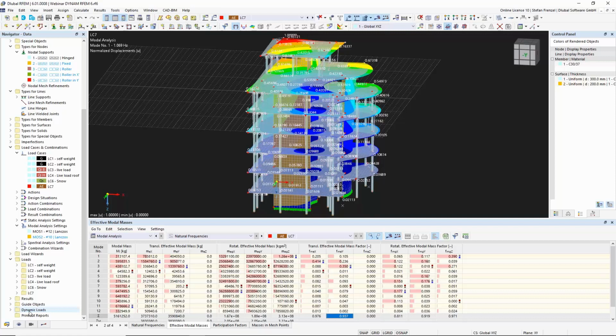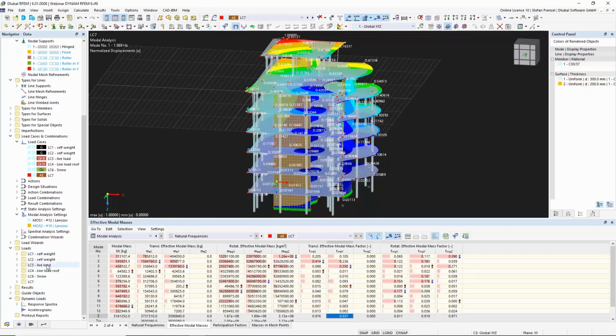The dynamic loads are also important, because in the dynamic loads it is possible to create response spectra and also to use accelerograms from real earthquakes. Those are recordings from real earthquakes, and with these accelerograms you can do a calculation of the response spectra. Sorry.